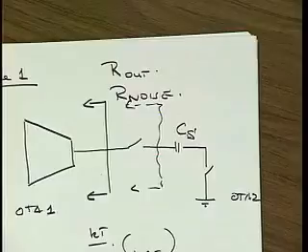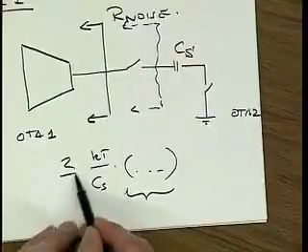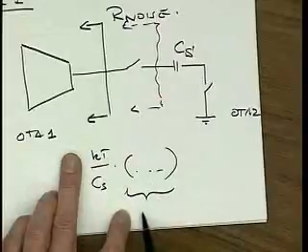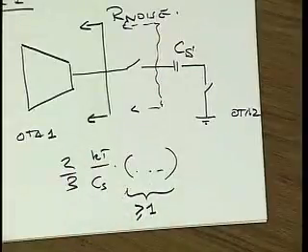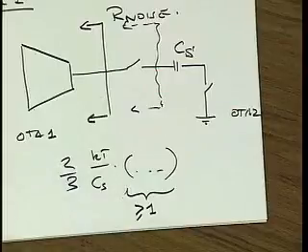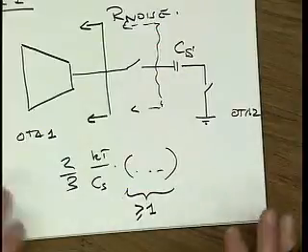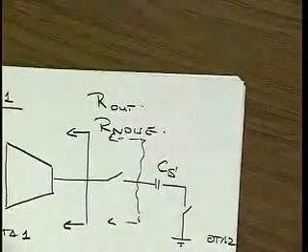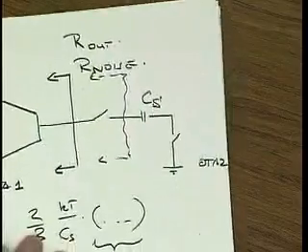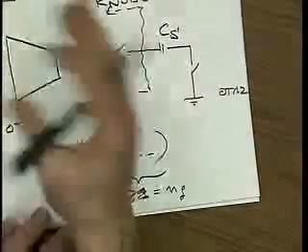Most of the time we get extra noise. If you do the homework, you will find that this factor, ignoring the 2/3 there, is always larger than or equal to 1. If you have infinitely large supply voltage, then maybe you can make this factor just 1, but not better than that, with the amplifier that you have in the homework. There are other amplifiers, and then the factor is something different again. So in practice, I usually call this factor NF, the noise factor of whatever is driving.